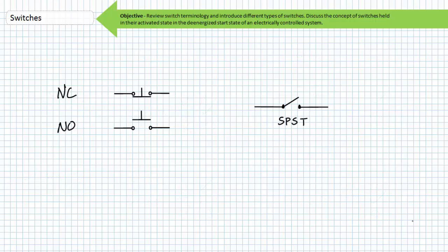Notice I'm using a slightly different schematic than the single-pole, single-throw toggle switch we've previously employed. The single-pole, single-throw toggle switch was something known as a single-break switch, in that there is a single point where the single pole breaks or makes its contact with its single throw. This normally open and normally closed switch on the left-hand side are still kind of like SPST switches, because each switch has one moving contact, and it can only be placed in one position.